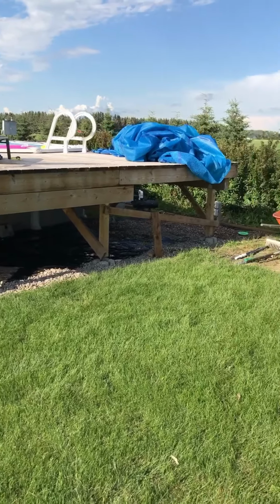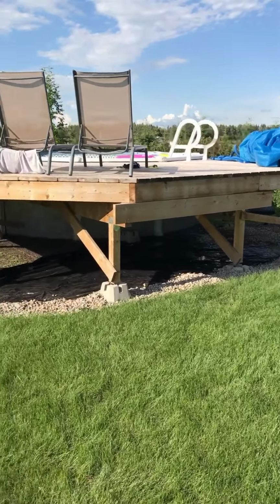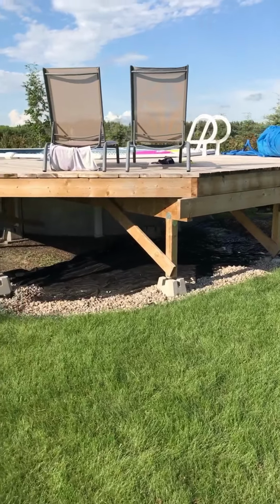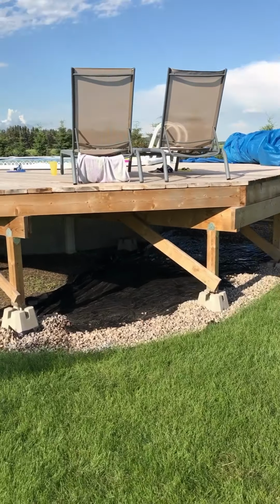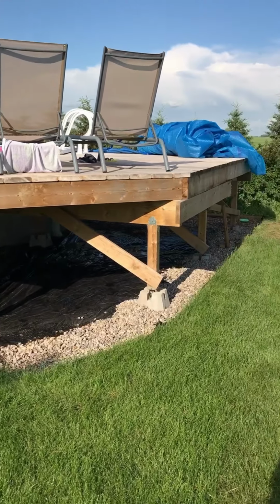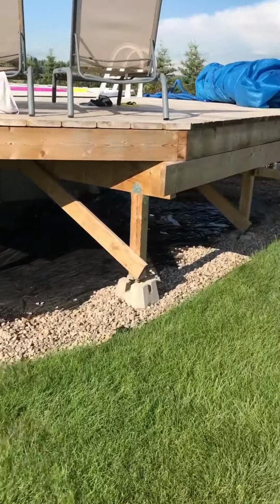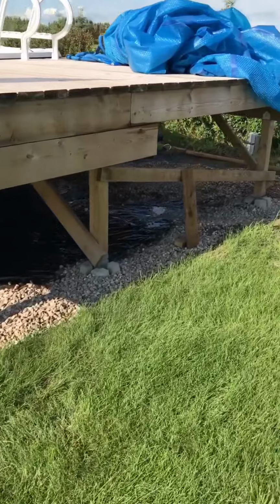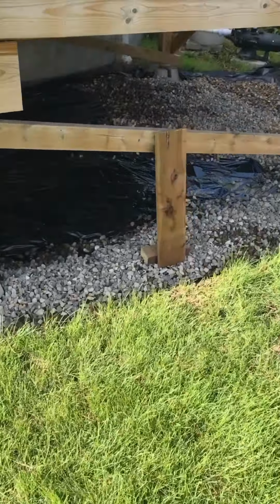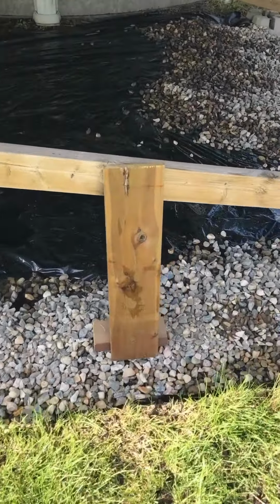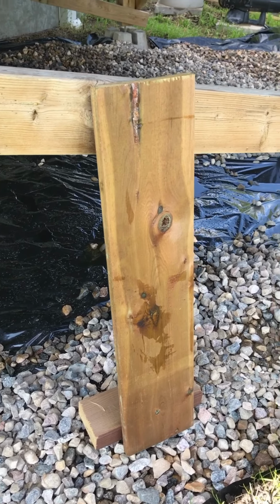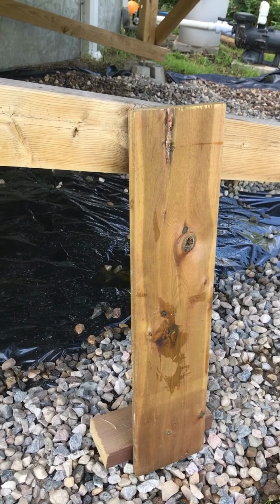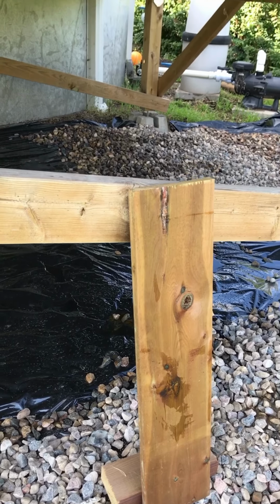I just want to show you a project that I'm working on right now. It is an unusually shaped deck around our pool, and I want to enclose the entire deck with a kind of vertical wall around the outside, and I want to do it with vertical fence boards. So the template here of what we're working with is going to be a vertical fence board like that, and a 2x4 on the bottom to anchor it down, and then we'll probably run another 2x4 on the top as well to nail that too.